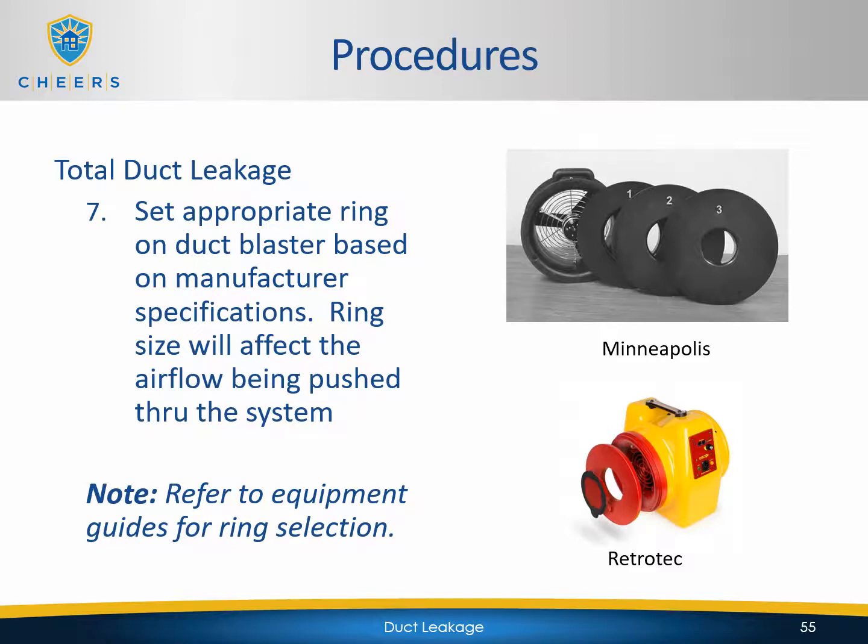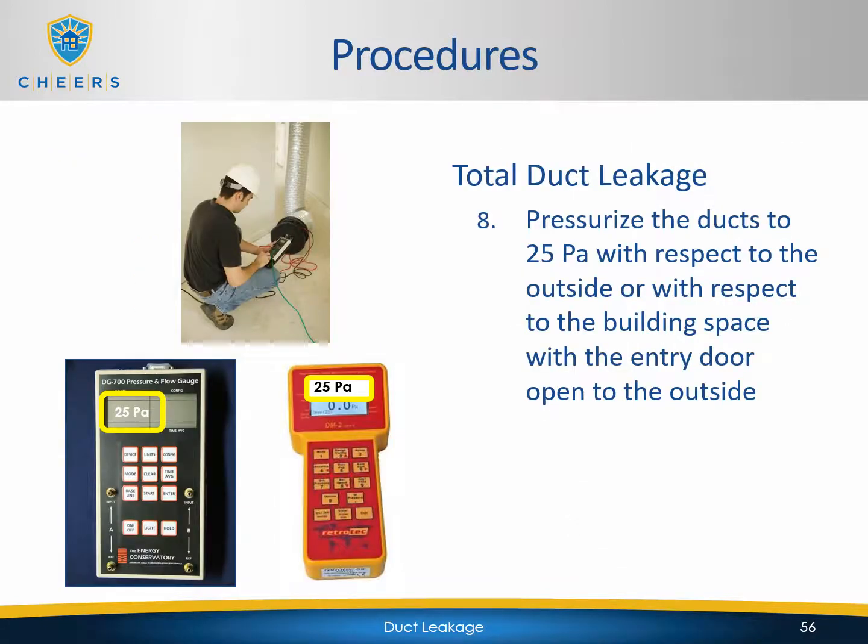experience with that. Again, here in this PowerPoint, we're just letting you know what you're supposed to do as far as the steps so that you'll be able to recognize what to do during the actual field training. Then you're going to set up your manometer, and again, you'll be setting up your manometer hands-on during field training. And you're going to pressurize the ducts to 25 pascals with respect to the outside or with respect to the building space where the entry door opens to the outside.